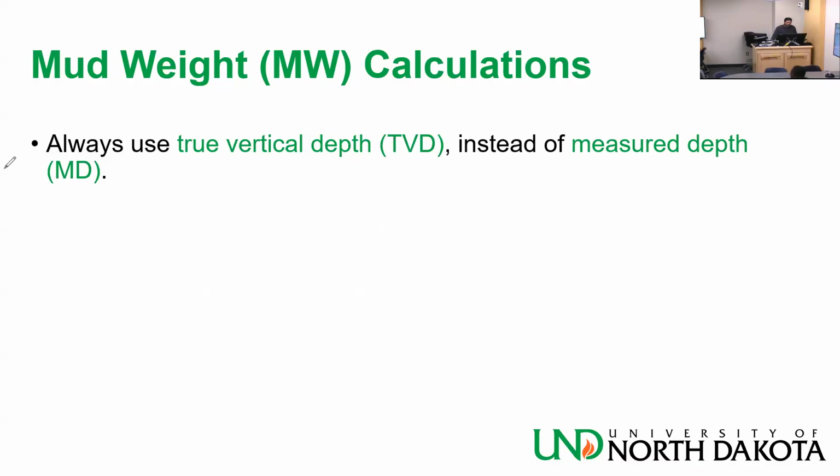But when it comes to hydrostatic, when we say the hydrostatic weight of this fluid column, we really mean rho g h. Sometimes in the oil field we say the pore pressure of my reservoir is hydrostatic, and it implies that it's the same as if you had fresh water all the way to that depth.